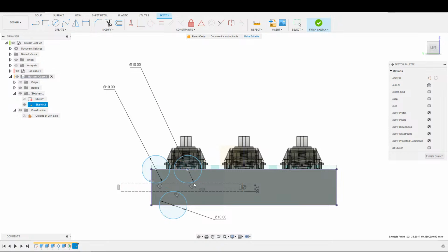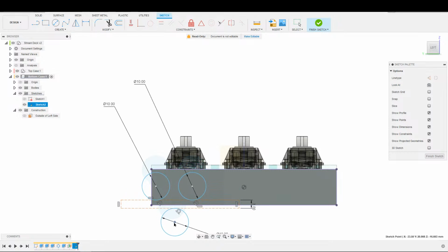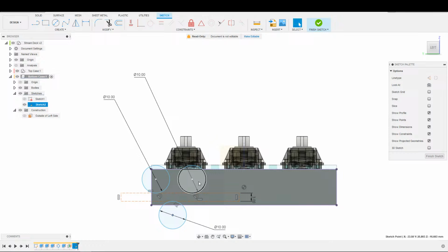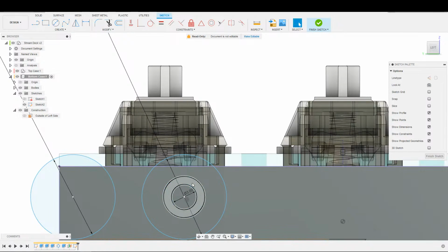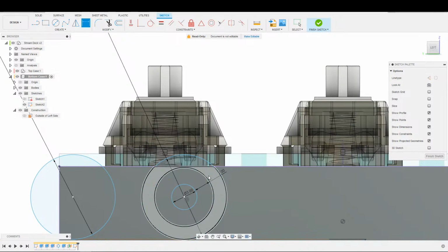The problem is, as you can see, that these bearings, and it looks like I just locked that guy too. Okay, let's see here. Something is locked in place here, so I can't move it down, but oh, it's this guy right here. There we go. So basically, I would have to, and this is a 3 millimeter hole, and 2 millimeters of meat right here. Yeah, 2 millimeters of meat. So I'm just getting the size that we'd have to make this bottom case in order to accommodate this setup is what I'm mapping out right here.